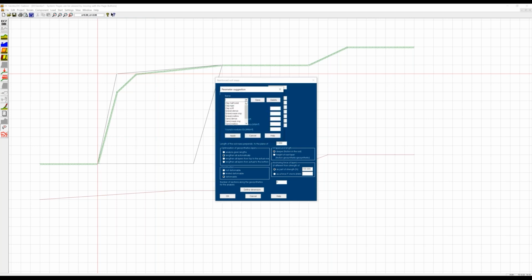Here this could be some gravel, for example. And we can define to calculate the required length of the geosynthetics layers or we calculate the predefined length of the geosynthetics to know if we have the sufficient safety level for this calculation.